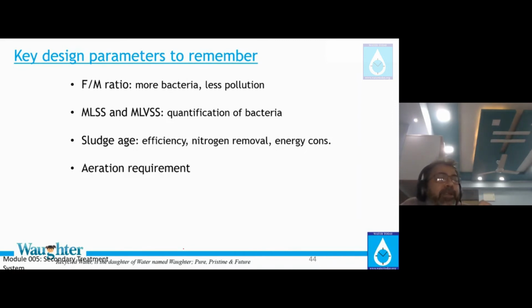So when you are designing a wastewater treatment plant, you will think about, sir, whether you will have 100 KLD flow immediately or you will have 100 kiloliter flow over a period of 2 years. So he'll say, oh, over 2 years. Right now, some flats are empty. So initially, there could be only 50 KLD. So you say, okay, sir, then I suggest you have 2 blowers. Half capacity blower will start with. We will run the second blower when it is required.